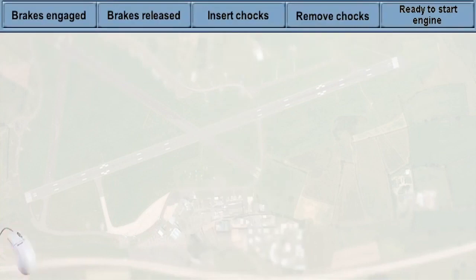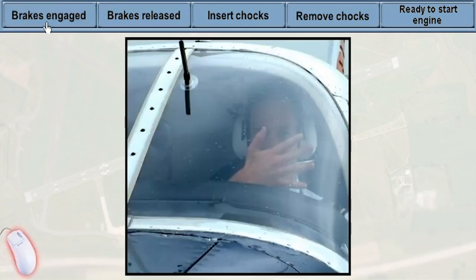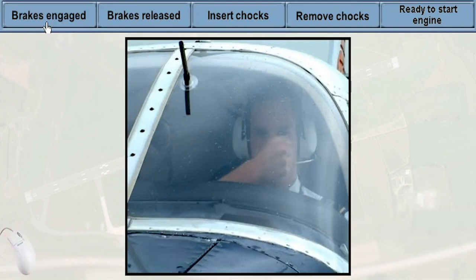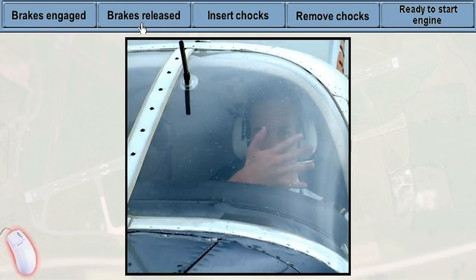To assist with the maneuvering of aircraft on the ground, a standard system of signals has been developed for use between the pilot and the aircraft marshaller. Raise the arm horizontally with the fingers extended in front of the face, then clench the fist. Raise the arm with the fist clenched horizontally in front of the face, then extend the fingers.